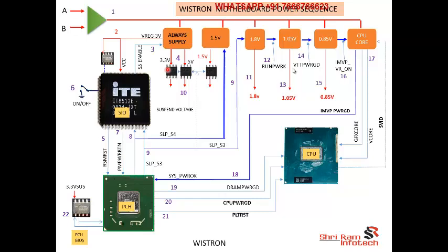Okay, so these are the different pulse width modulator sections. Once this 18 voltage passes to the different pulse width modulators, they wait to get an enable signal. They will not start until they get the enable signal. Only this section will respond and generate a VREG3.